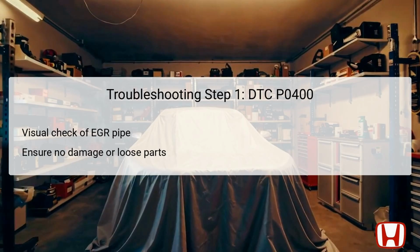The first step in troubleshooting DTC P0400 involves a visual inspection of the EGR pipe. This inspection is crucial to identify any visible signs of damage or looseness in the pipe that could be causing an EGR system leak. Carefully examining the pipe's integrity can reveal problems such as cracks, corrosion, or misalignment that may not initially be apparent during normal operation.